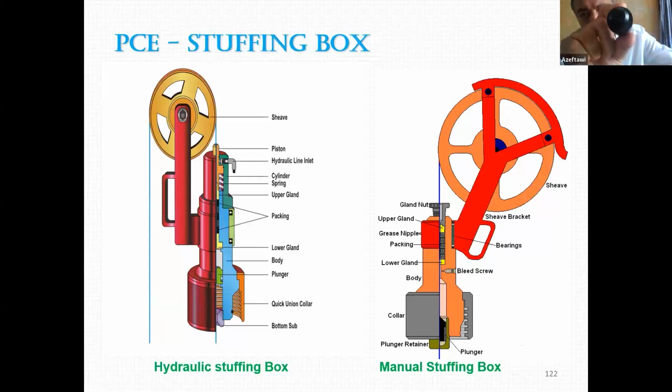Yes, I know that it has a hole in the middle. But you see this upper part? The upper part is rubber, while the rest is metal. This upper part is rubber, so it will be squeezed to go inside this profile and act as a blind. And that's why this plunger, we call it stuffing box BOP. We call it plunger. We call it blowout plug. All the same meaning, all for the same part.